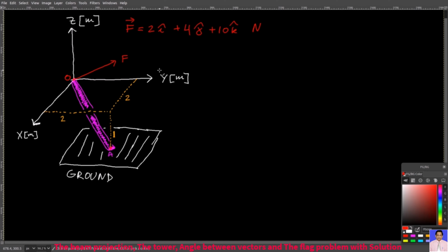Thank you very much. Welcome back. So this is where the dot product is very useful. You have the xyz components of the force vector, and you want to get the component of that vector along this beam. And so in order to do that, you first want a general unit vector from the point where the force is applied, so from the tip of the beam. Let's call this general unit vector UA with respect to O.